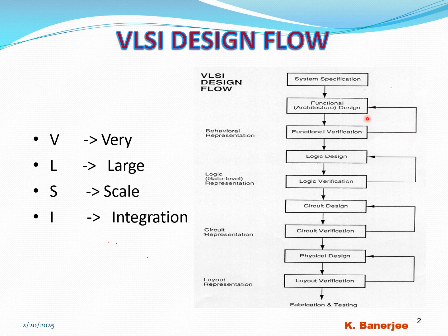The third stage is logic design and logic verification. In this stage, the control flow, like register allocation, and arithmetic and logic units that represent the functional design are identified and designed. The logic level design is actually the gate level design.